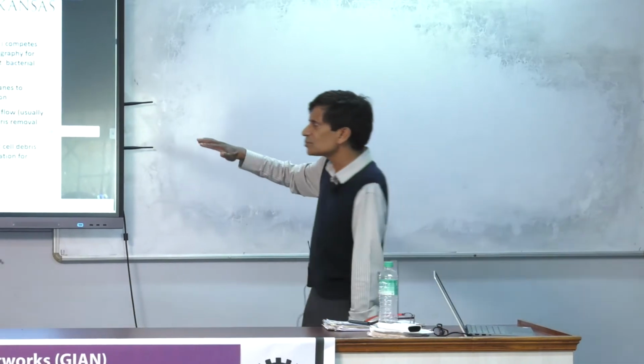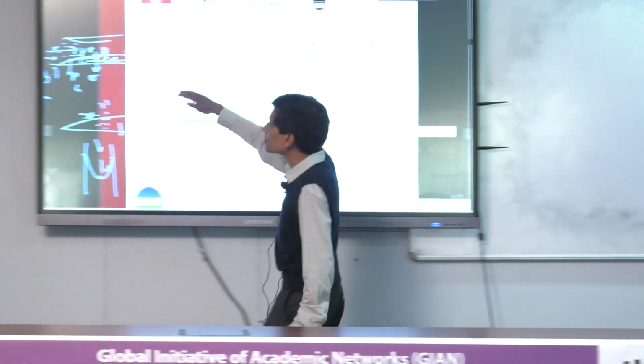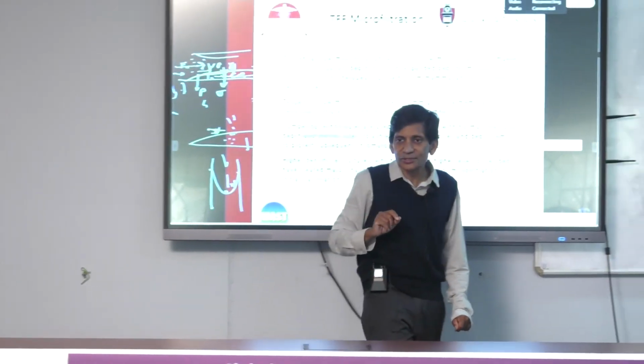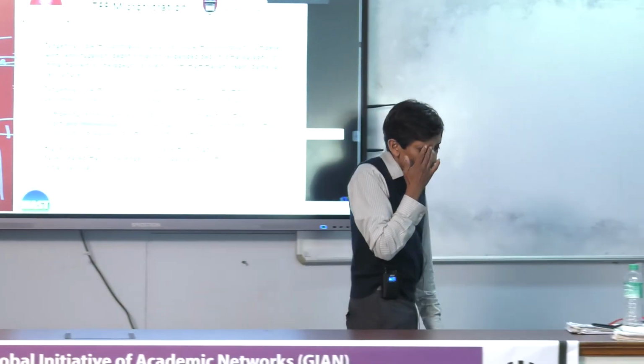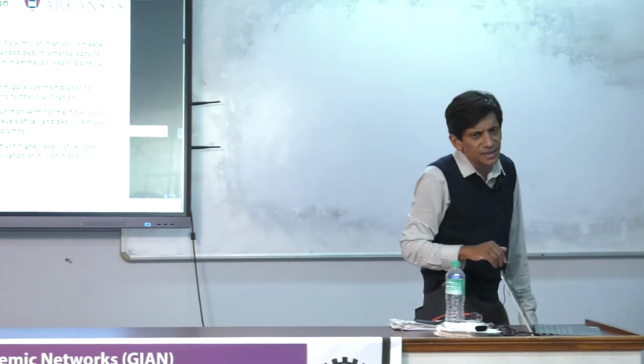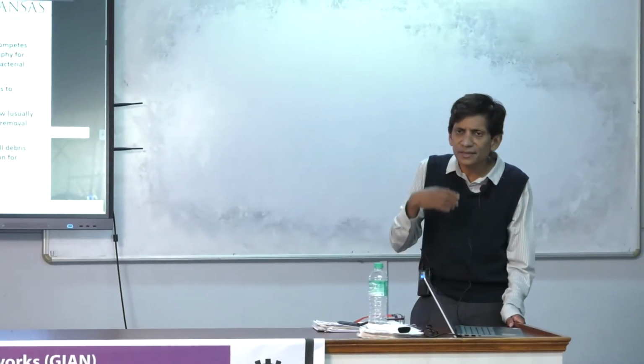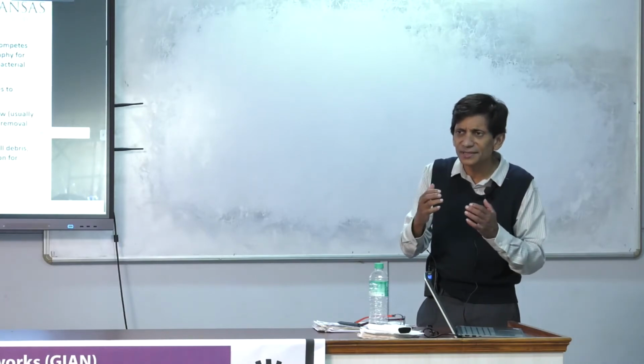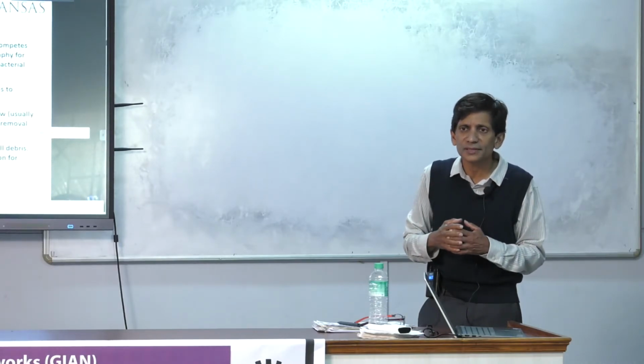But again, the deposition won't occur forever. It'll stop at some point because this channel is becoming more narrow. But you will get deposition, okay? So there's a lot of literature on this critical flux idea. I would say this, it is an interesting concept. It gives you some idea in real applications, at least qualitatively, what would be a good operating condition.